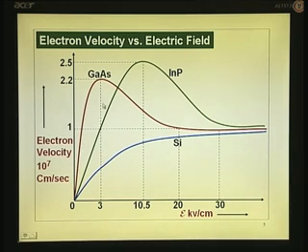For electric fields lower than 3 kV per centimeter, electrons are all in the lower valley. So, they never get transferred to the upper valley. They do not enjoy the benefit of going through that peak field, personifying the electrons. They will just get accelerated to that steady state value, and they remain there.